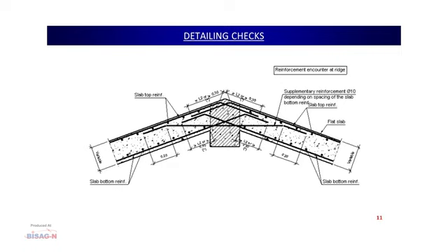On the top bar, whatever is coming, we can also do a similar type of bend up. This bar is taken over here, given a bend here. Similarly, this is also taken, given a bend here. And in addition, we can provide a 10 diameter rod or bar across this. This provides more rigidity and sanctity to this junction. In all the cases, under whatsoever load is coming, the cracks in the central portion of the beam will be avoided if we go by this kind of detailing.